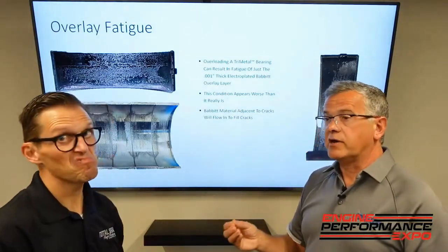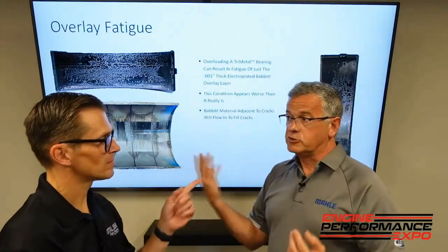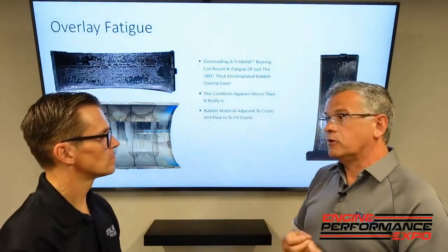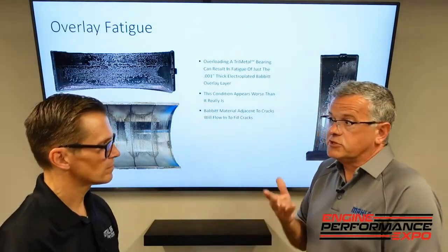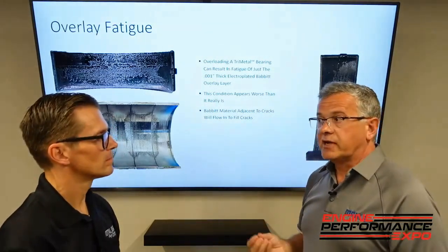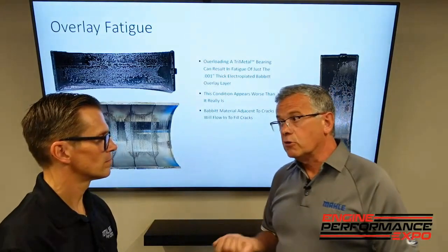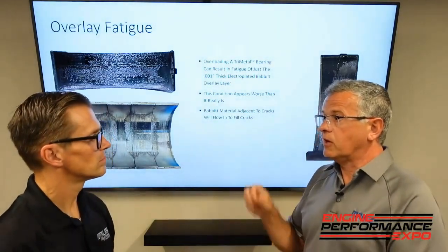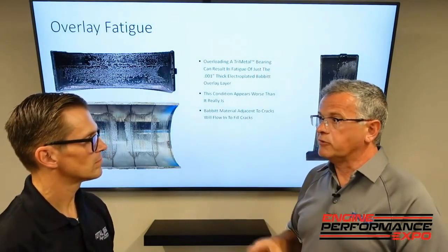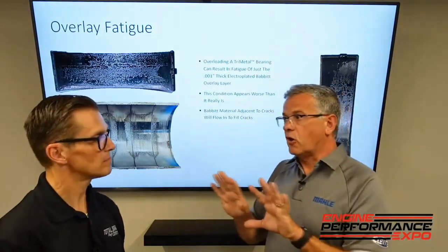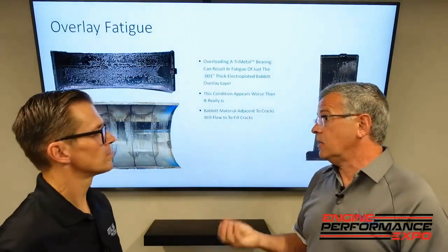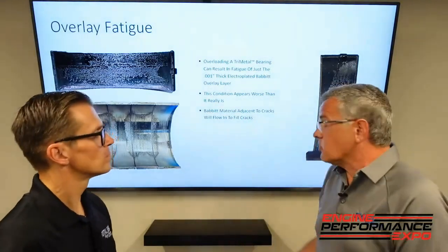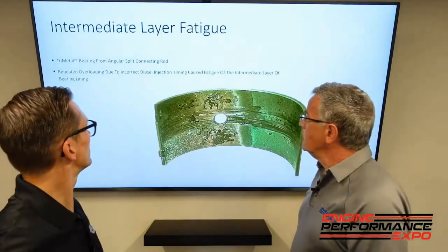Right, because you can't create grain structure unless you change it from an element to an alloy. Right, you got to melt it. Yeah, you have to melt it, so you get better adhesion. You don't get the cracks that you do with sintering, and that's why typically a cast bearing is 20 to 30% stronger to prevent fatiguing, because it becomes an alloy of bronze with lead that softens it. That's so cool. All our H and V bearings use a cast, which we own that facility, and that's where it comes from.